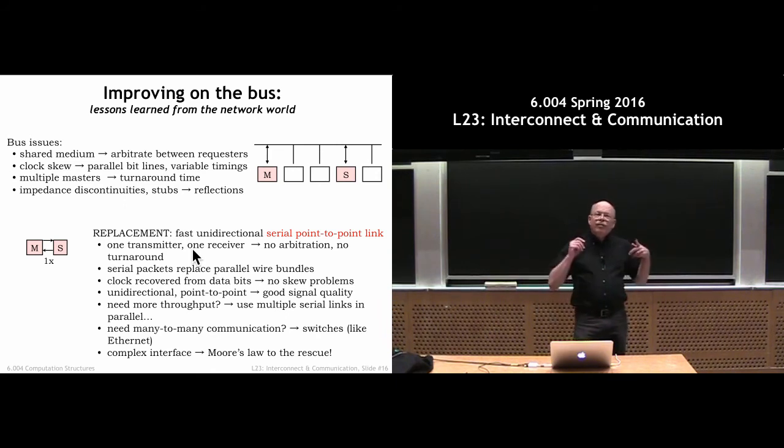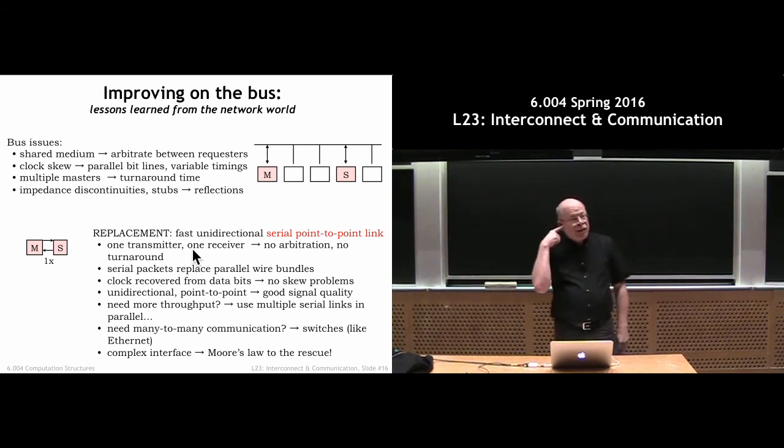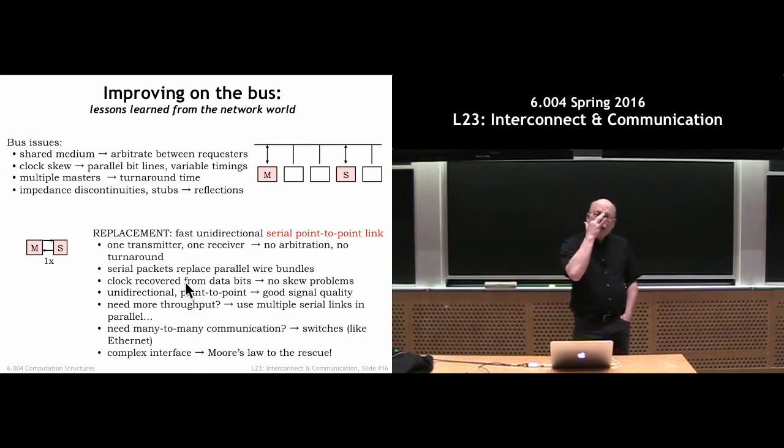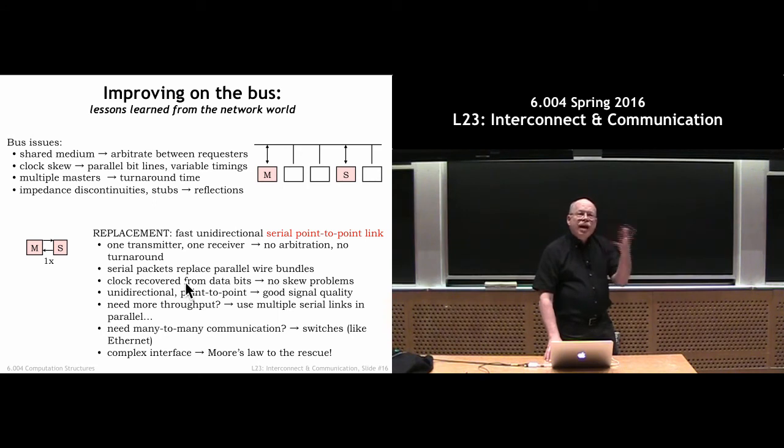Alrighty, so point-to-point communication, one transmitter. There's never a notion of, wait, now you have to send to me, so I have to get off the air, and then you can start transmitting, and how long do you wait before you start transmitting? All those problems are solved if I can always yell in my send signal and always listen to my receive signal without any protocol about whether I should be listening or sending. So that's very great. All packetized, all covered by checksum, so I can tell when a packet has failed. All using a clock recovery scheme, so I can just send you the data and you can reliably extract the bits in the packet without any other information than that single received waveform.